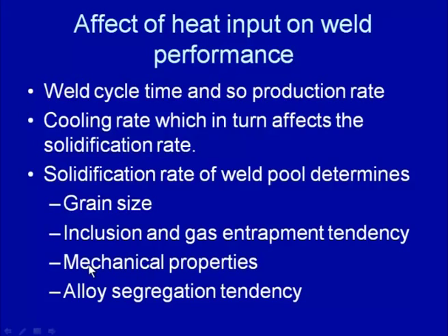So, if somehow we can avoid the presence of inclusions and gases in the weld pool, then it will always be favorable to have the finer grain size using the higher solidification rate, which can be achieved by reducing the heat input to the weld pool. So, if a finer grain size can be produced in the weld, free from inclusions and gas entrapment, then the mechanical properties will certainly improve.